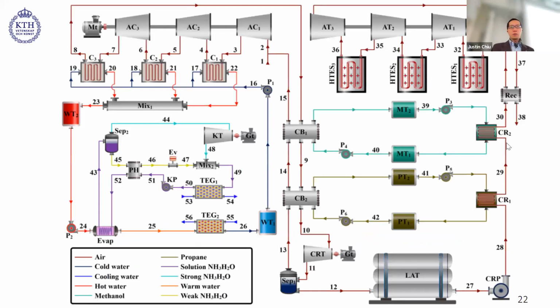So here, to understand how this works, first you need to see the arrow, like which direction it goes. Here we see on the right hand side, you go from high pressure to low pressure, right? Because the shape of this is large here and small there. So here you have an expansion. To the right here, you have 3 stages of expansion. This is when you discharge the liquid air. And then to the left, this is the charging part, or charging equipments.